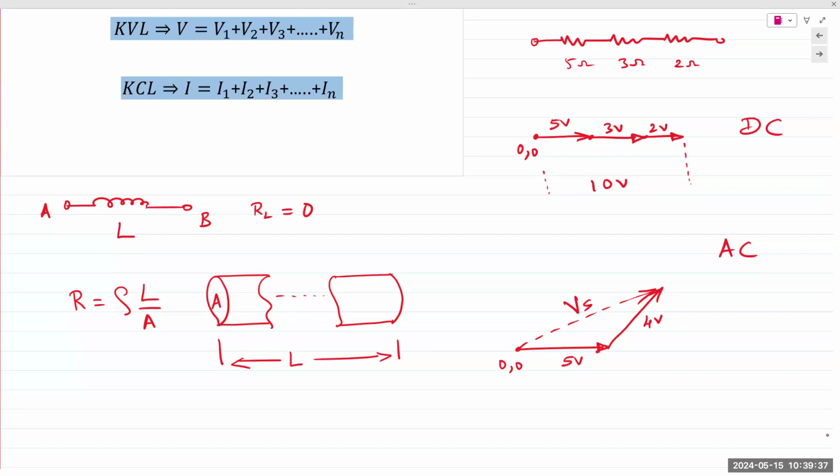If you take this inductor and measure the inductance between A and B, it would give you some value for L. If you take the exact same inductor and measure the resistance between A and B, it will give you some resistance value also, because it is physically part of the exact same component. You cannot separate those two out. The resistance and inductance measured between A and B come from exactly the same physical component, but are two different electrical quantities. Does that make sense?